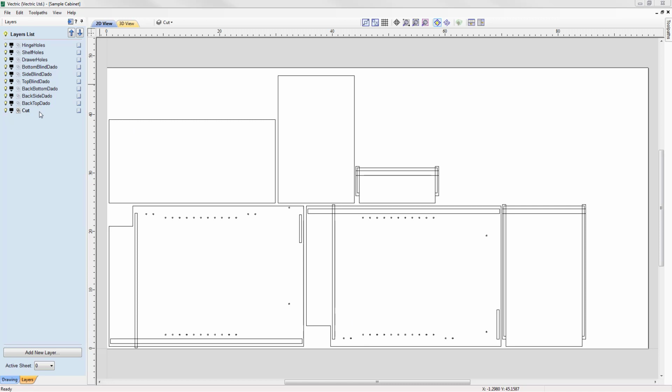And so any further cabinets that I decide to make in the future in this particular software, when I come to import them in, it will have the same layer information and the vectors relating to those layers, so that when we do come to utilise the toolpath template, it's going to look for the particular vectors that we specify on the particular layer that we've selected and then apply a toolpath to them, which in the long run will save us a lot of time. So let's take a look at the layers and see what we've got.